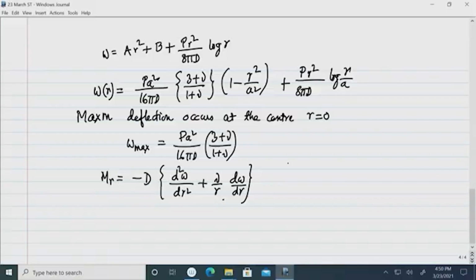So, the axisymmetrical problem I have fully discussed now, and I hope that you can now proceed to tackle the problem of a circular plate subjected to axisymmetrical conditions, that is on the boundary and also with respect to load. Okay. Two formulations are necessary, one is the shear equation and another is the deflection equation, that is relating the fourth order derivative to the load. Any of these two equations you can apply depending on the conditions of the problem. Okay, thank you.